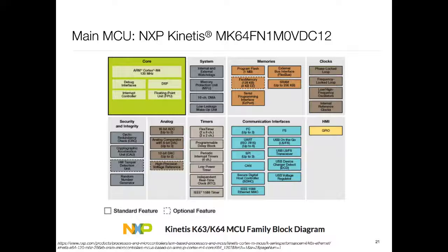I2C, UART, SPI, CAN, these are all examples of commonly available serial interfaces through which sensors and actuators connect to it. For example, some of you might have played with things like Arduino, right? They provide particular ways of connecting shields and things like that to the main board, but the various pins usually correspond to the analog IOs and these kinds of serial devices to connect. And then finally GPIOs, which are basically uncommitted pins, which you can twiddle 0, 1, or where you can read the signal coming in.